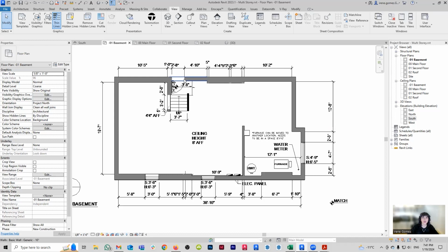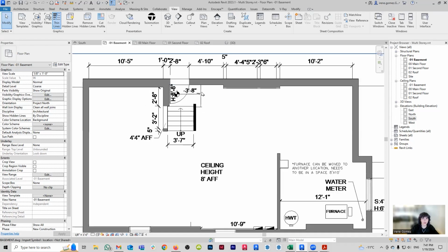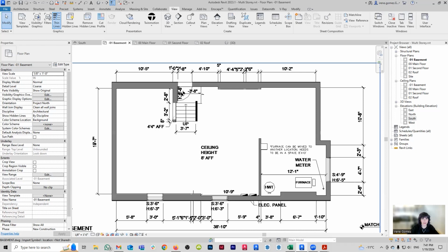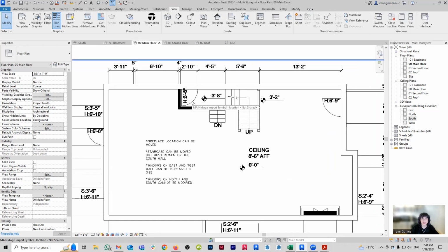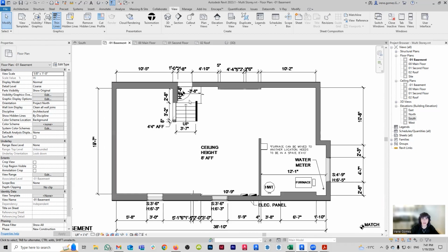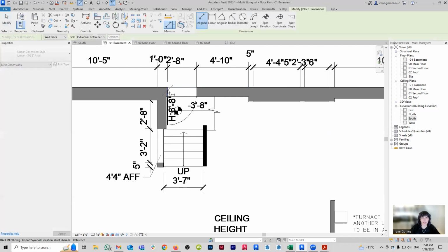We're probably going to need to do the same thing here with the floor, because with this door, you can see that it is at a certain height. This 6'8" is probably 6'8" from this level here. Let me see what it's telling me, 6'8". Yeah, I think this height of 6'8" will be from this level here. So I'm going to set my door. What is the width of my door? Distance to it. Oh, okay, so it's this number here.